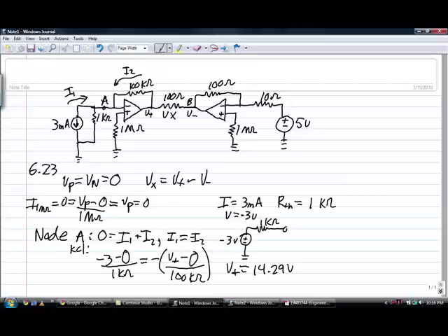Now let's look at the right-hand side of our circuit. That is much easier. We don't have to do any source transformation, and we already proved earlier that the voltage across this is 0 since there is no current going through it. So let's do our node equation. We'd still again have the I2 is equal to negative I1. Well, that's actually backwards, but who cares? We'll just do it that way.